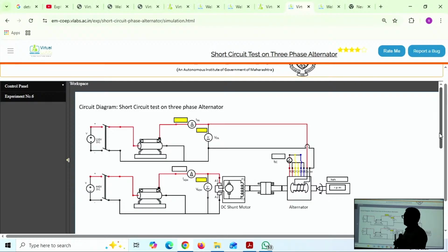Again, fundamentals. We can tell the students that the use of star delta transformation now comes into the picture. If it is delta connected, what voltages and what currents? If it is star connected, line currents and phase currents are the same, and line voltages are different, √3 times the phase voltages. We use this in starting of three-phase induction motors. For the same power rating, we get reduced voltage, which is required to reduce the starting currents in case of motors. That depends on the connection. So here we connected. That's it.